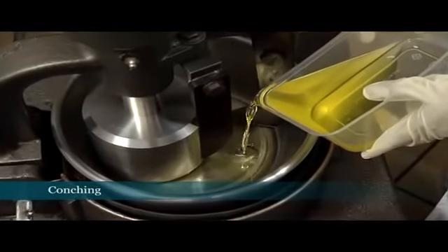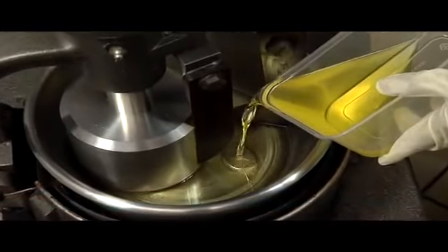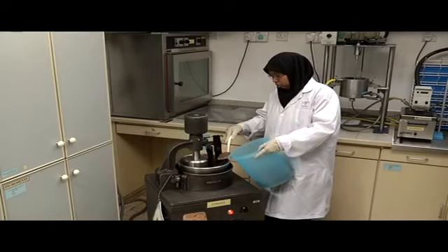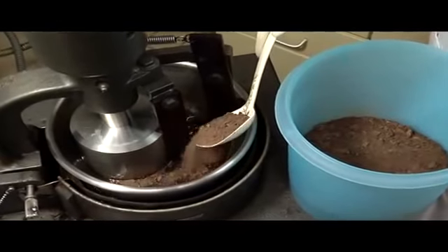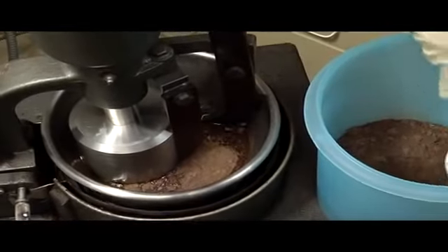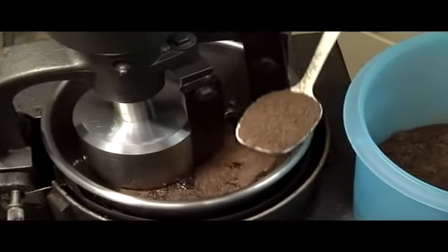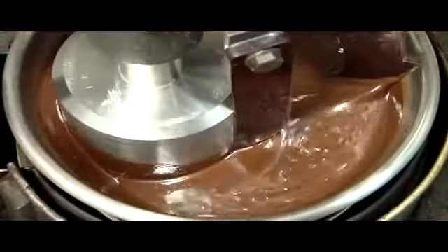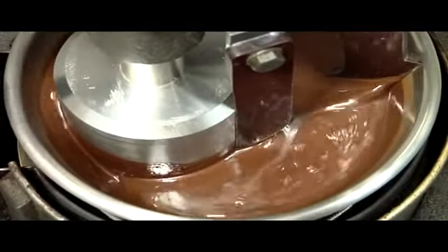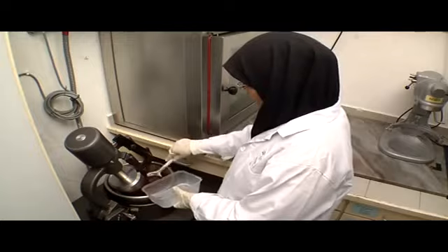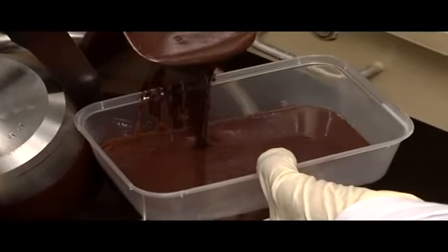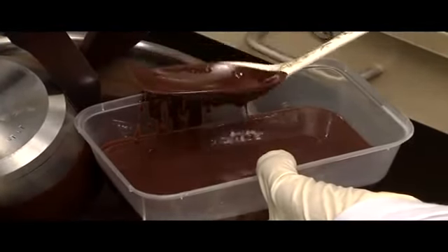Conching is a decisive process to produce good quality chocolates as physical and chemical changes occur for the development of flavor and flow properties. Temperature control is between 65 to 90 degrees Celsius for plain chocolate and 50 to 65 degrees Celsius for milk chocolate. The duration is dependent on the composition of the mass, but it is normally more than 3 hours and often longer for plain chocolate. A homogeneous product mass is produced in the homogenizer.